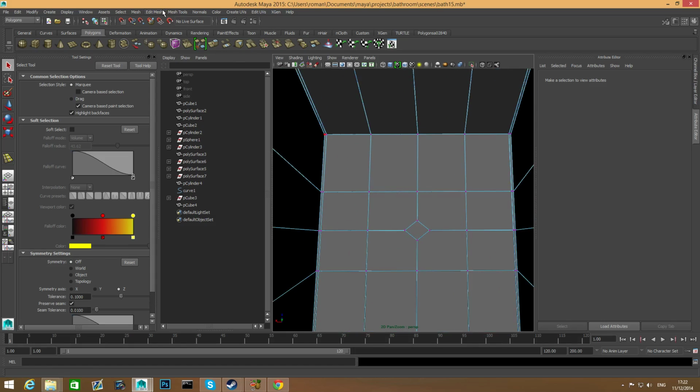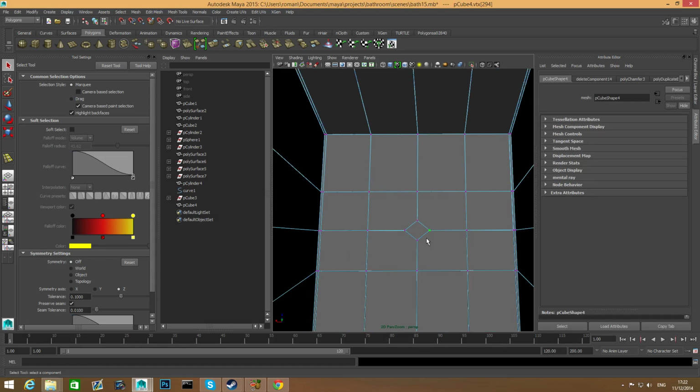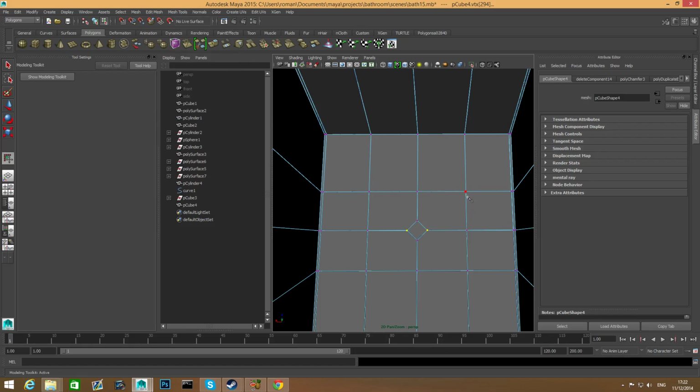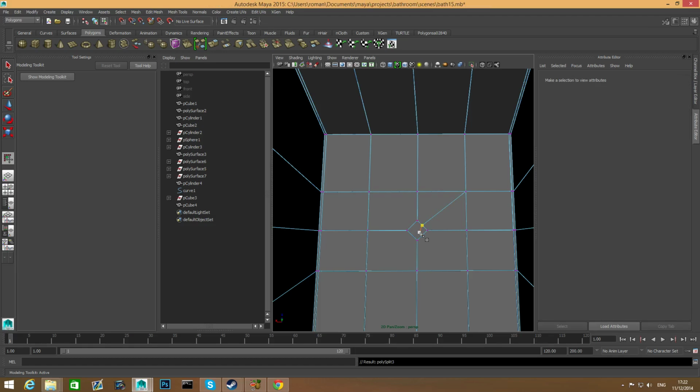We're gonna grab these 2 edges with the selection tool, at least those 2, squeeze them so it will be even square. Mesh tools, multi-cut tool, click, release, click, hold, drag, shift to close on the 50%, and then right-click to close this. Well, first release and then right-click to close this, and then again, and then again, and just one more time here.